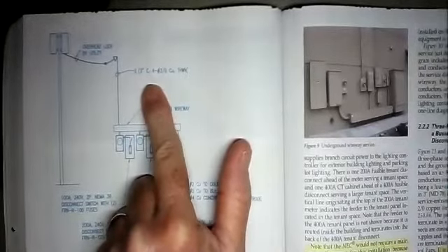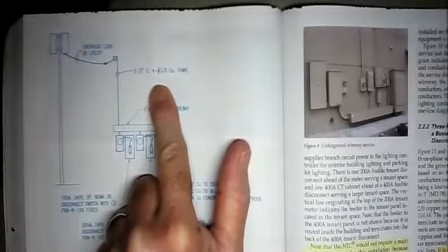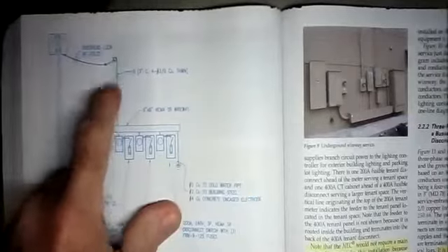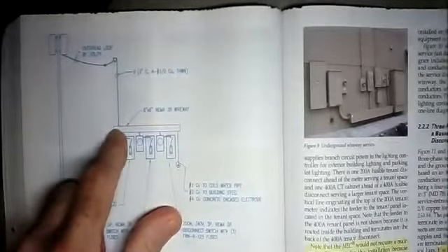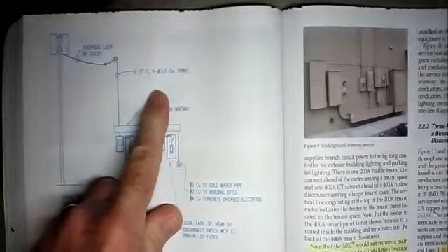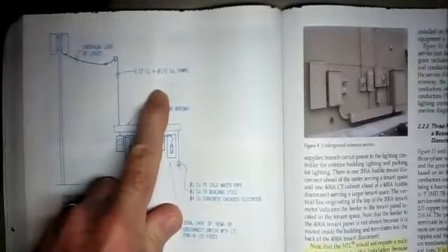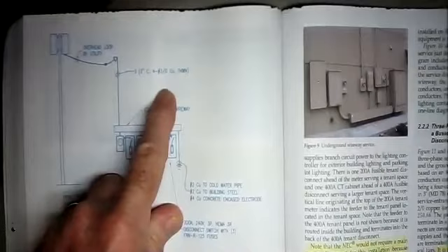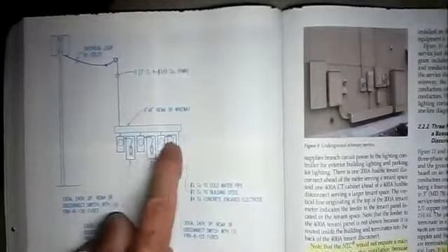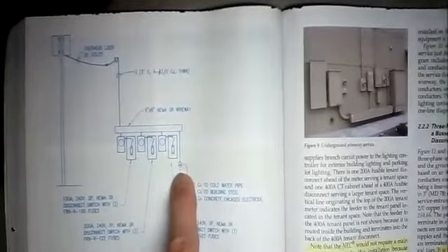2 2-inch conduits. They have 4 3/0 copper THWN. So they have 2 2-inch conduits coming down, and each conduit has paralleled 3/0 conductors for each of the ungrounded phase conductors and the neutral into this trough. And then the ground would be established here. Here's where they're establishing ground.